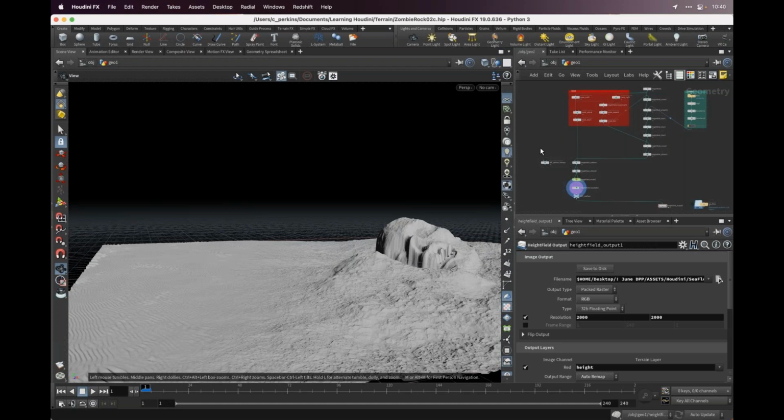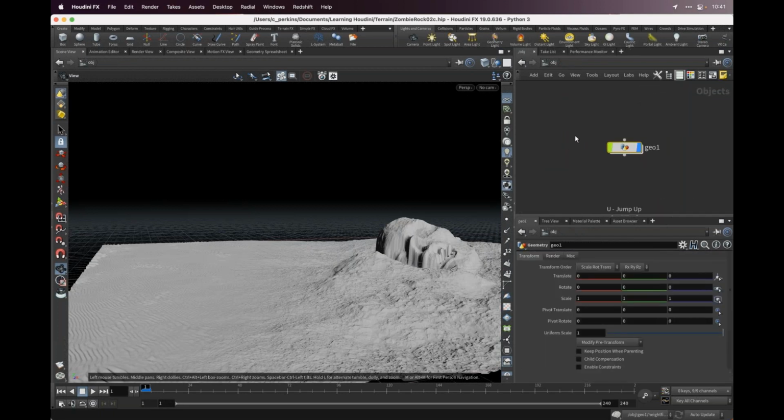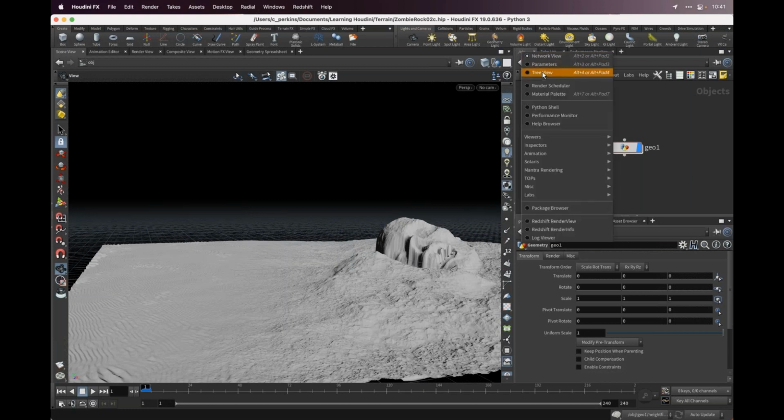Houdini has a thing called HeightFields, which is basically terrain generation, and it's an extremely powerful tool and actually very simple. If you're looking to get into Houdini, HeightFields are by far the easiest thing Houdini does, where you can do something really powerful but it's also really easy, because not many things in Houdini are very easy. When you first launch Houdini, you have this network view, and right here you have the properties panel. If I right click on the tab here, I can choose whether I want to see the network view or the parameters. So you can change your interface very easily that way.